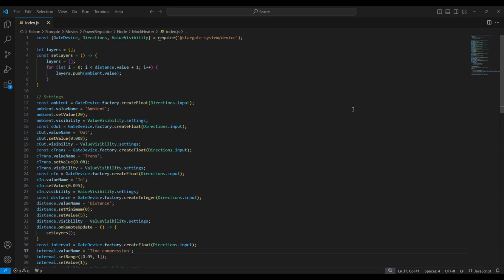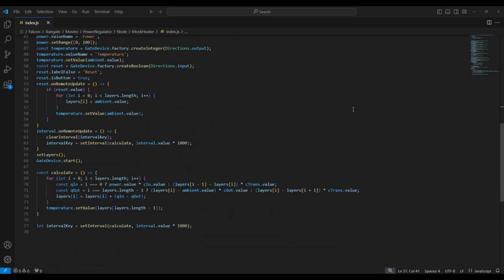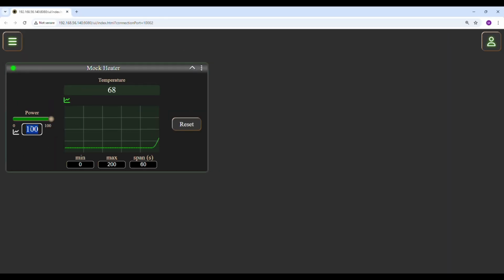First layer will represent internal temperature of heating element, last one temperature observed on the thermometer. On each subsequent iteration, I will increase first layer temperature proportionally to current power set point and redistribute heat throughout the following layers. Finally, I will dissipate a portion of heat from the last layer proportionally to actual temperature difference to the ambient. The code is fairly simple, now I just need to adjust parameters to get desired characteristics.